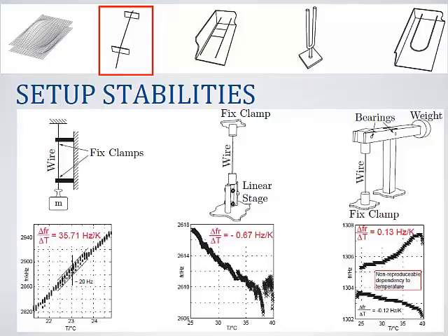Now I want to show you measurements with first approaches, setups, and problems we had with these setups. The three structures which you see on the top left are double clamped structures. These double clamped structures have the disadvantage that they are very cross sensitive to temperature. What we see here are the evaluations of resonance frequency for the case of a straight wire.